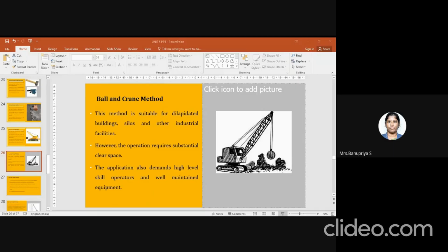When you do concrete bursting or hydraulic bursting, it doesn't produce much dust or much noise. Okay, so this method is well suited for removing mass concrete or brickwork, foundations, pillars, and concrete walls. Instead of demolishing the entire building, if you want to demolish a particular component of your building, you can go for pressure bursting.